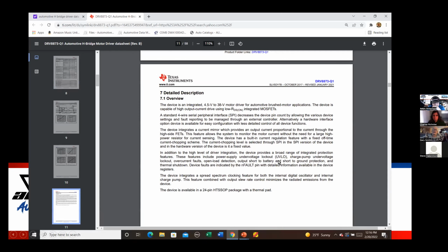That's under voltage lockout. So it is really, really important, since a lot of these cars will not set under voltage codes from, let's say, a battery that's falling down a little bit on initial crank in cold weather. And we're going to get that throttle motor or that Valvetronic lockout right as soon as we start the car, because the battery dipped down to 8 volts and then came right back up to charging system voltage. Of course the car runs, but now guess what we've got? We've got a chip protection strategy in here that defaults the throttle motor, and now it gets towed into the shop. You want to know why it keys up when it's fine?